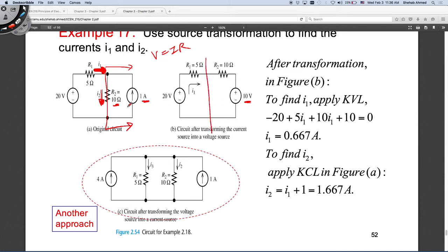So it's 10 volts. And the Thevenin equivalent resistance is equal to the Norton resistance. So I take this 10 ohm and put it here. So now I have a circuit that looks like this. With this circuit, it's very easy for me to solve for I1 in this case. I1 is equal to what? The current flowing in this circuit, these are two resistors in series, right? So I look at the voltage here and the voltage here, right? I go around the loop. So this is what? My Kirchhoff voltage law around the loop.